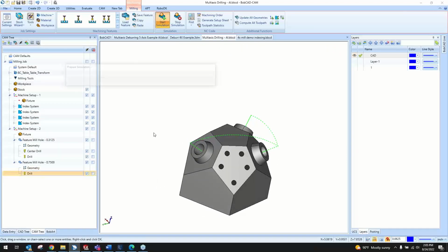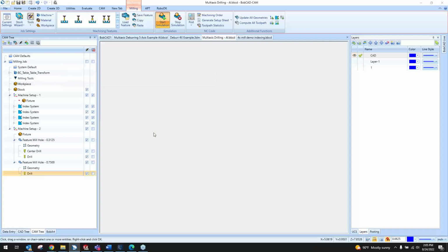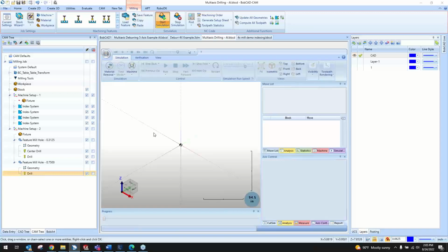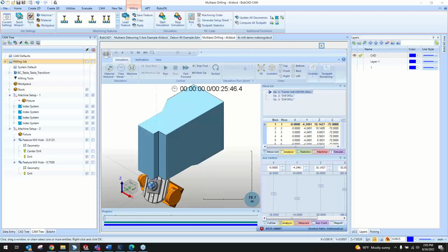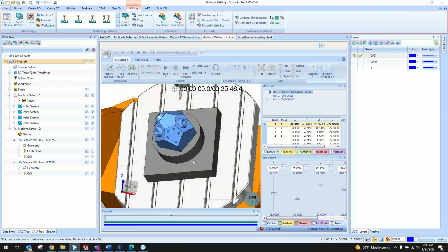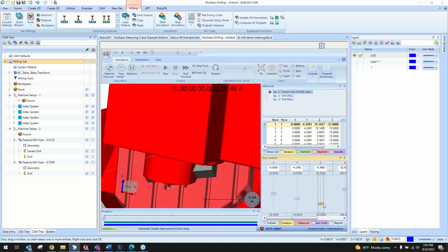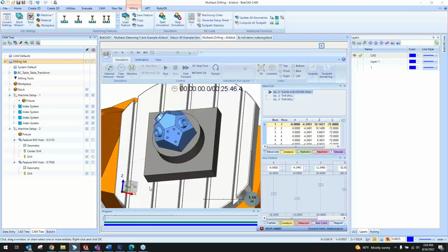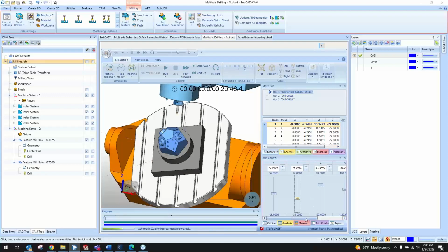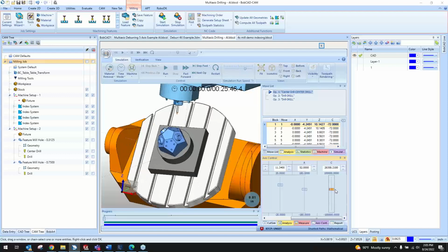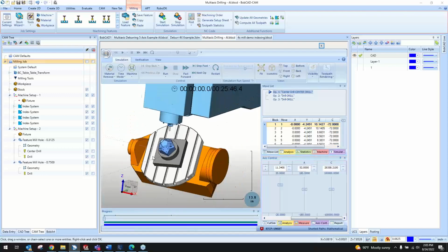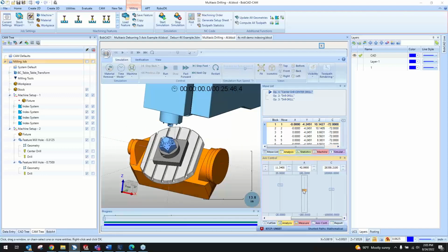So in this simulation, we had a machine with a rotary table on it on the previous one. This one will be a 5-axis rotation where we have a platter that will rotate around the z-axis. Look at this here. We've got the axis control here. We can see that. Oops, sorry, that's the z. We want c rotation. Then we can see we can rotate the platter around, see the rotation of that, and then we can rotate the a-axis around, which would be the trunnion.